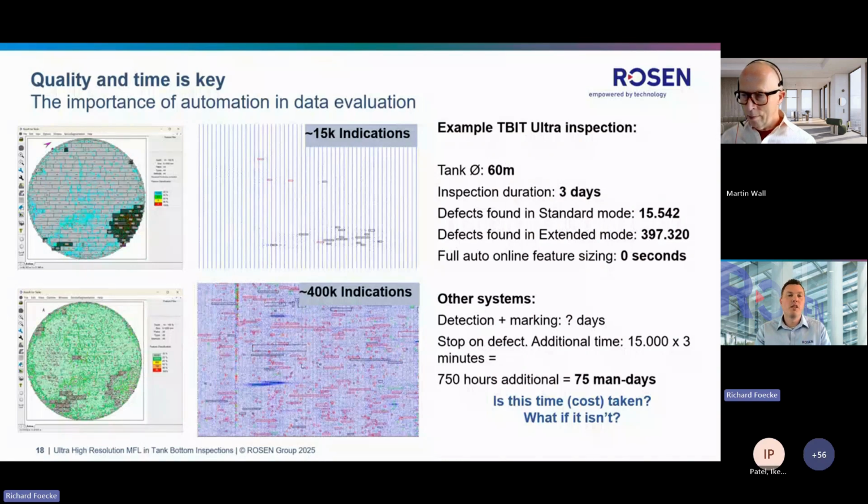So we measure the lift-off inside the tank continuously with eddy current sensors. And this value is immediately considered in the MFL sizing on the feature depth, length, and width. So therefore, lift-off plays a role from a performance perspective, but we calibrate our tools on this lift-off and we consider lift-off measurements on the fly in the MFL sizing process.